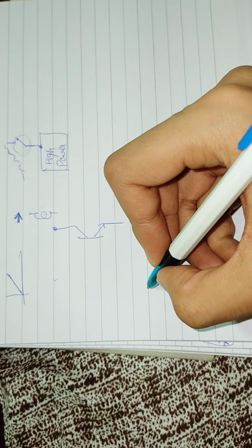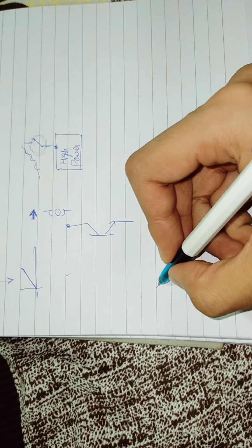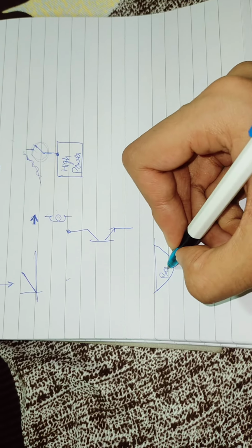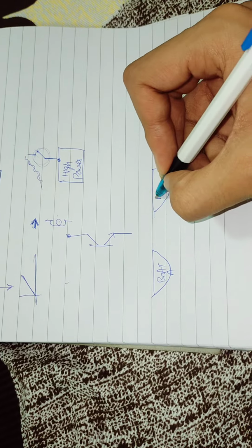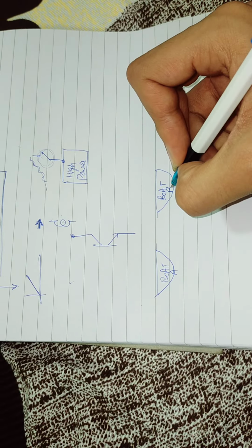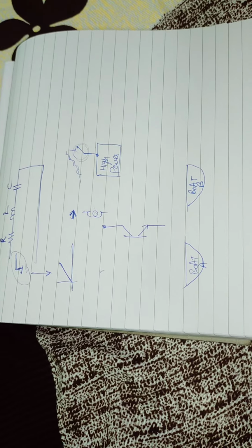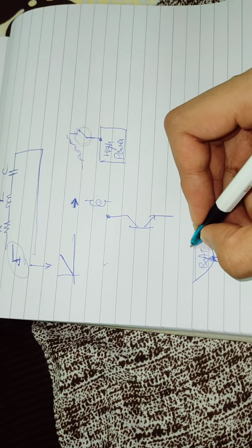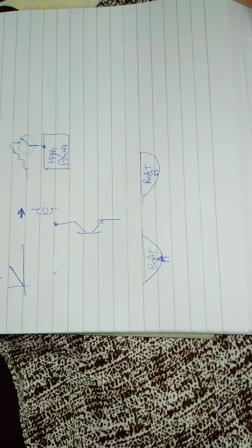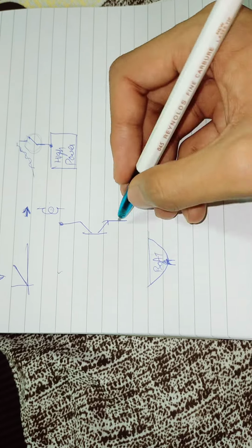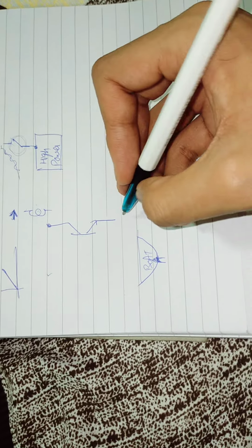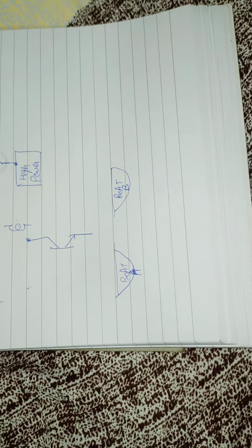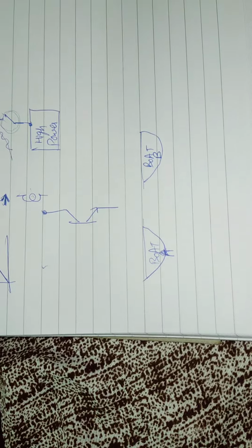And one question was like there are two boards, board A and board B, and we have to perform data transmission from board A to board B, and we don't have any antenna or any kind of things. So how will we transmit data? We just have a set of parallel wires and a few digital circuits we can use, but we don't have any wireless transmission circuit. So this question was based on application of shift registers. So this thing also they asked.